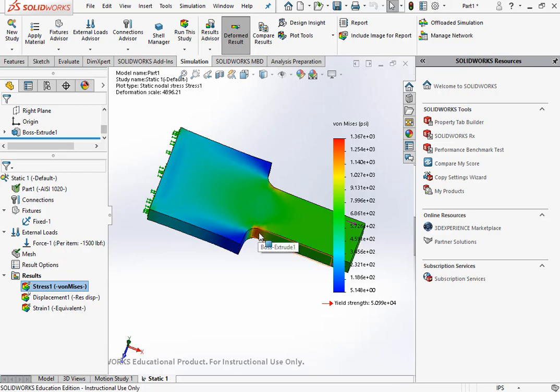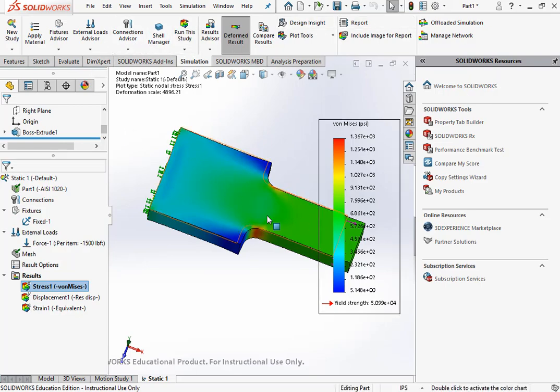Maybe you don't like this high stress concentration, but then you look at it and it's like, well, that's only 1,300 PSI. That agrees with my theoretical results, and I think that's fine for what I need this to do. So you can do things like that relatively easily. And once you start really doing finite element analysis, then it becomes a useful tool for design, analysis, all this kind of stuff. On the exam, I'm obviously not going to have you open up SolidWorks and do this.